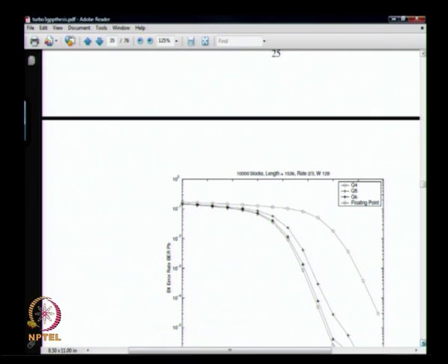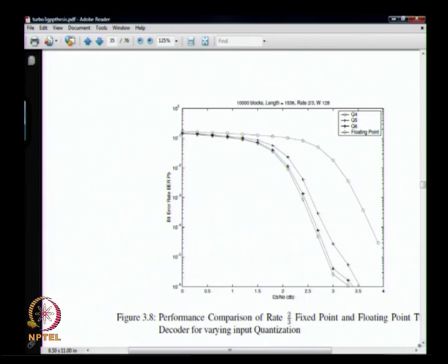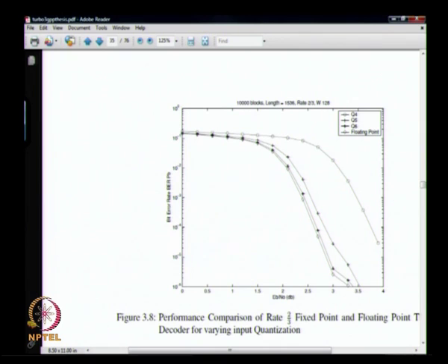So this is rate 2/3. This is also specified in the 3GPP standard. Once again you do similar curves, and you see there is some kind of a flooring effect at rate 2/3. This is what I mean when I say it's only for finite FER, of course. You can't really avoid these floors. So you get this at about 3.3 dB or so. For rate 2/3, again a significant coding gain at a higher rate. So these are plots that you have to do.